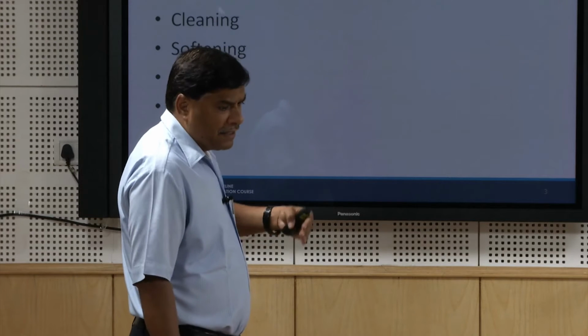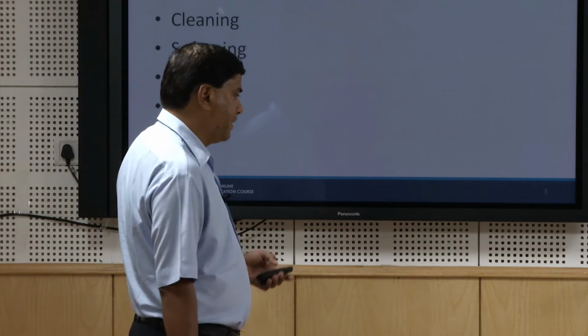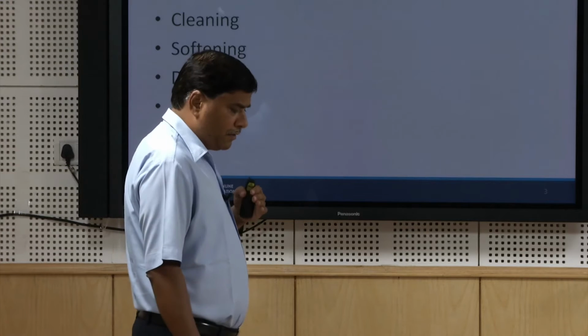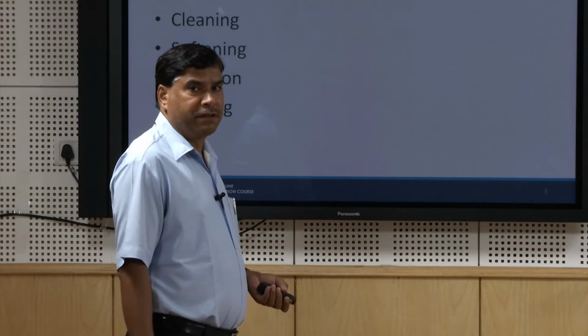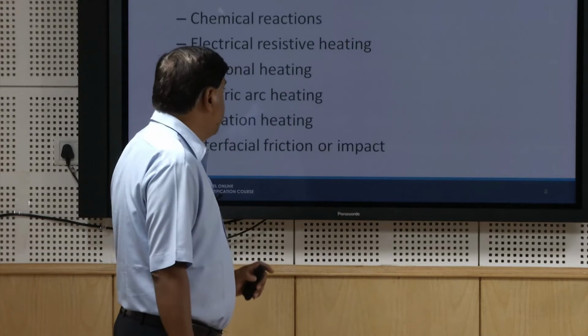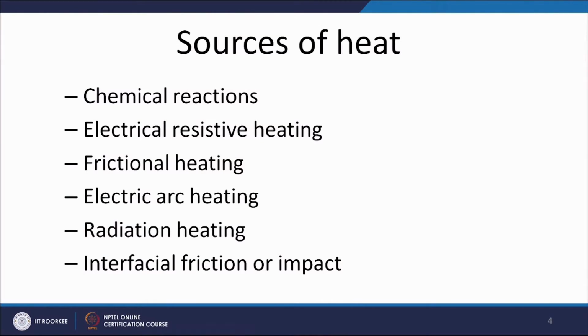The diffusion is accelerated at elevated temperature, so that diffusion bonding can be done in an effective way. And for the fusion welding processes, melting of the faying surface is facilitated with the help of the heat being applied.